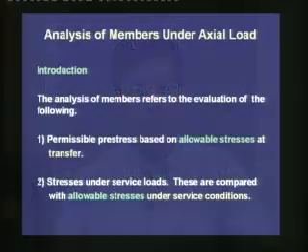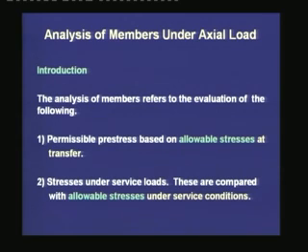Here, we are first studying the stresses at transfer, and based on the allowable stresses at transfer, the maximum prestress is determined. Second, we are studying the stresses under service loads. Now, these stresses are compared with the allowable stresses under service conditions. Remember that the allowable stresses can be different at transfer and under service conditions. We have studied the allowable stresses under the module on material properties.